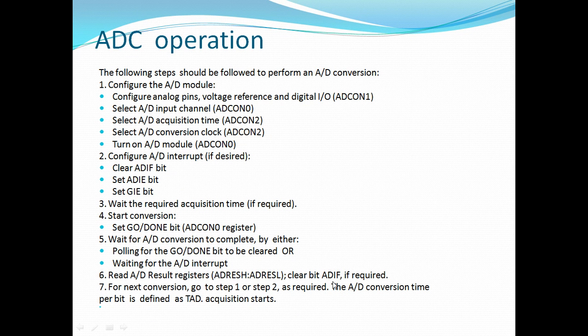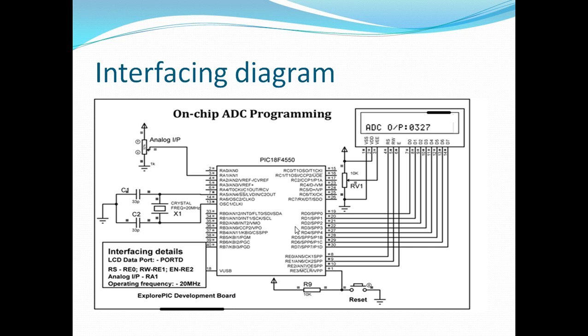So here the ADIF flag will be cleared. And we will follow these steps to have continuous conversion mode of the microcontroller or ADC. So these are the steps that one should follow for ADC operation, or for running the ADC module of PIC18F4550.